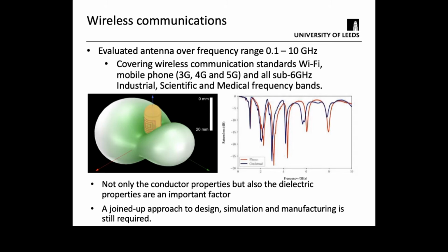One thing to note is that when you're looking at 3D printed, or I should say material suppliers from the industry, the few that give the dielectric properties will only list the properties up to 1 kilohertz, which isn't very useful when we're trying to go into the gigahertz regime. So there are some of these other ancillary challenges still out there. Another thing is that our process is a little bit ad hoc, I guess you could say, in terms of how you do the design, the simulation, and the manufacturing. And it would be great to see a much more joined up approach.